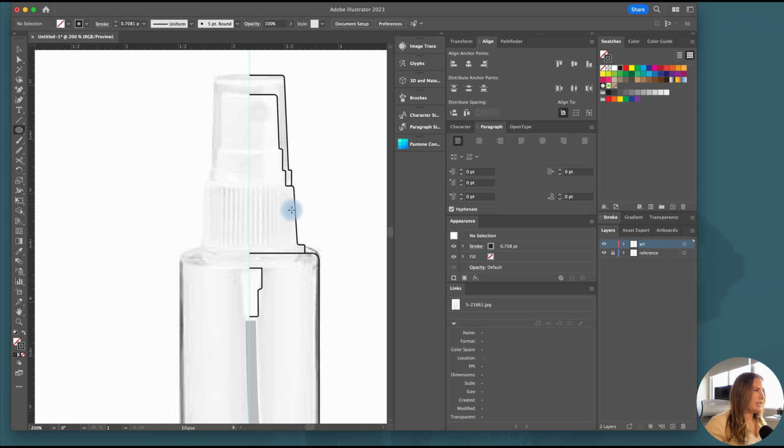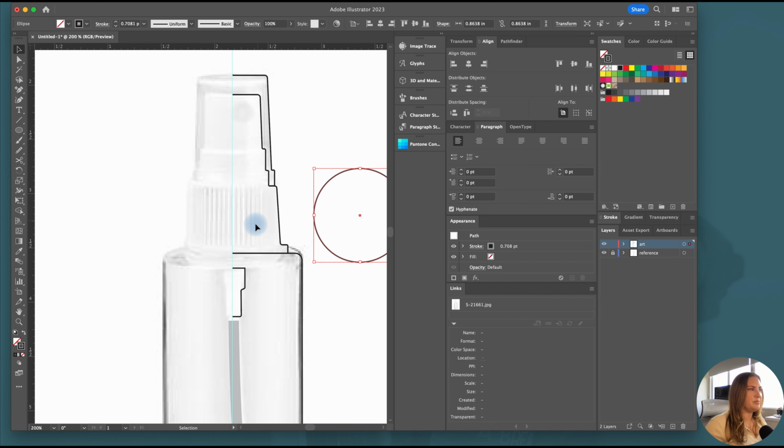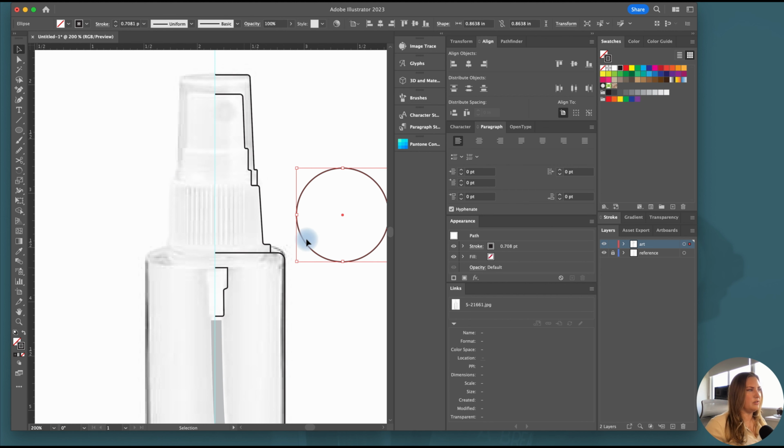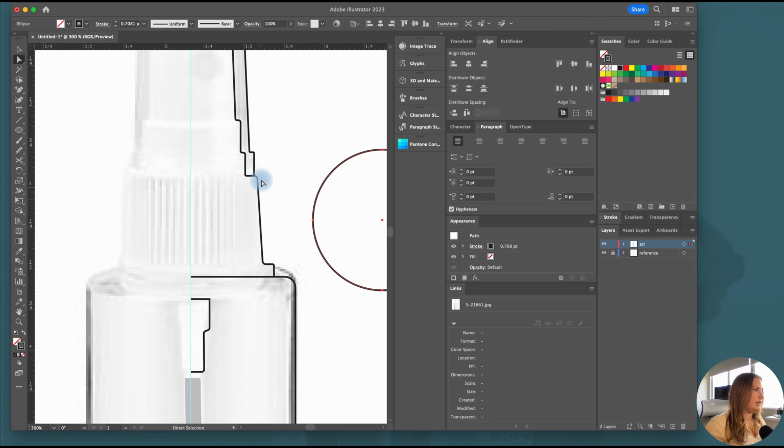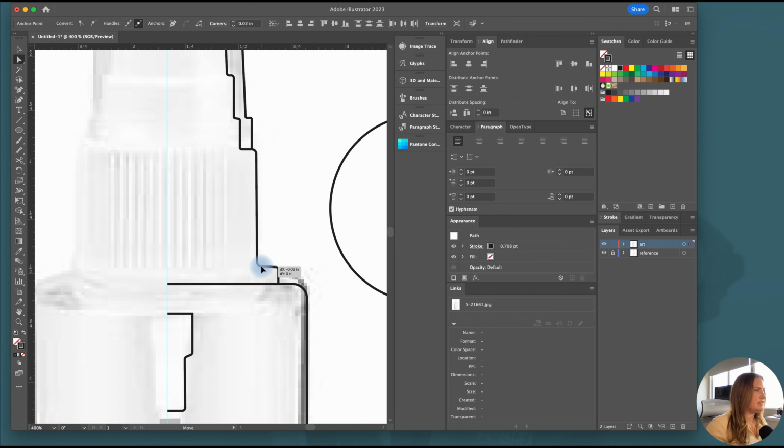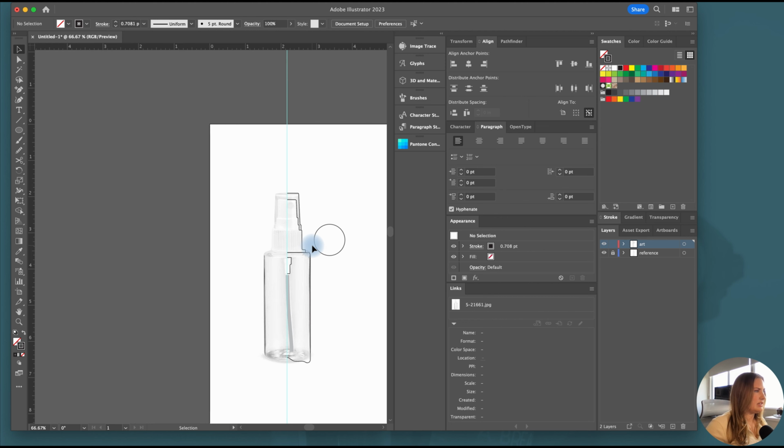Okay, and then the other step is to create a circle. So I'm going to hold Option and Shift, drawing an ellipse from the center point until it spans the entire width. So I'm drawing from that guideline out to the edge, because these will be the ridges that will go around this grippy part. And now that I'm looking at it, I might actually make this a little bit more straight up and down so that these ridges will lay evenly once we get to that point.